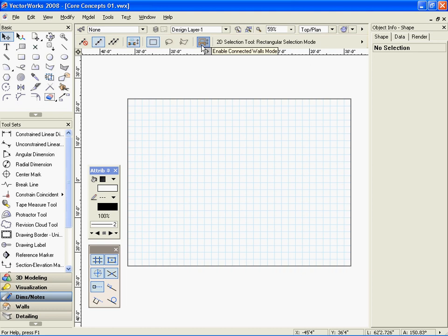In the second section of the menu, there are two options for activating the data bar. The first option is selected so the numeric keypad on the right side of a computer keyboard can be used to enter sizes while using floating datum. For the third section, choose Show Only Primary Fields on Data Bar, and for the fourth, use Large Exit Group button. You'll see more of how this fourth choice is used a bit later on.